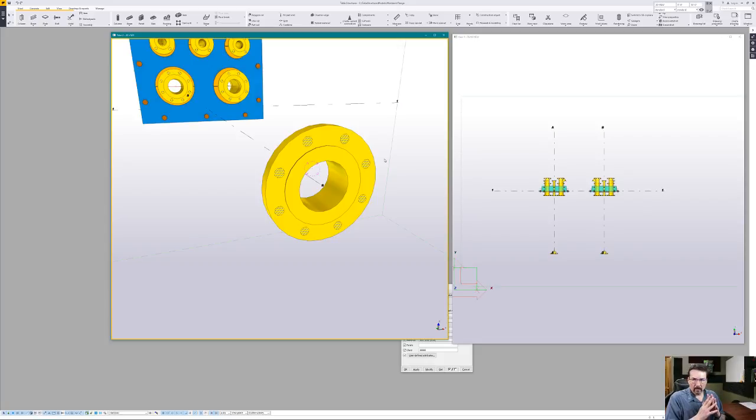And there are all kinds of profiles in the profile catalog, so you're not limited to just doing what I did here, but you can do this with just about anything. And if you can't find a profile that fits your needs, you can create your own using the sketch editor. I believe you can create your own profiles and put them in the profile catalog. You can use one profile and then hack and cut it up as you need to.